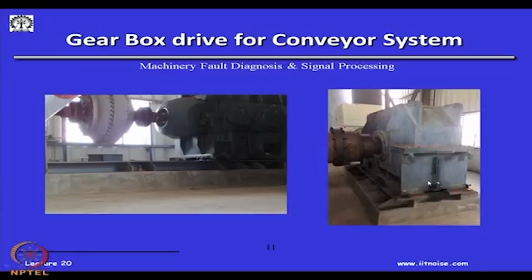So, obviously, you can imagine that this is near a seashore, and the seashore environment is very salty, with corrosive air blowing. This system was lying there for about 2-3 months through the monsoon and corrosive wind, and you can see a lot of corrosion occurring in the foundations here, corrosion on the motor base as well, and this will weaken the structure.